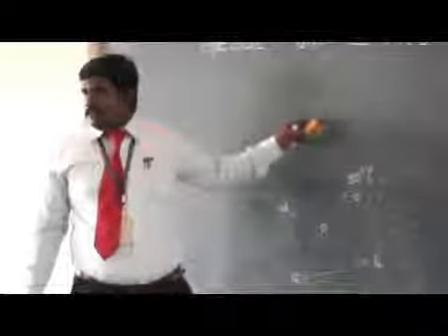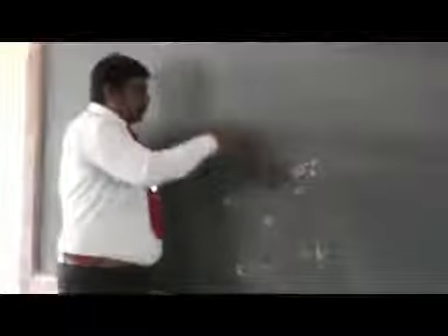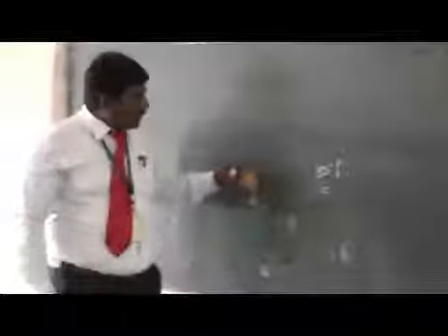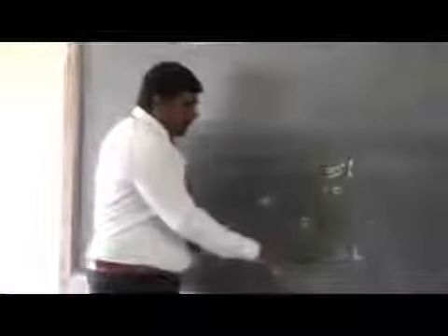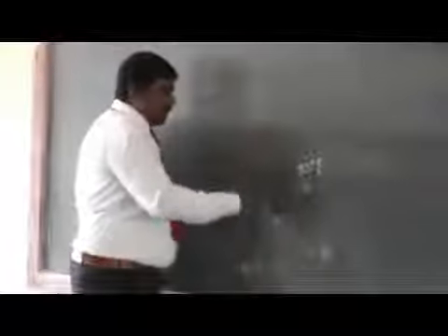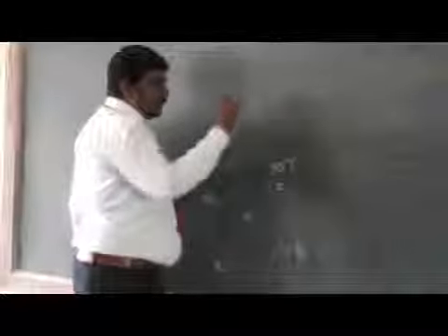Listen, 1 second. So to draw the front view of this, we have to project all the corners up to this reference line as we did before, isn't it? So now we just project all this using your draft scale so that all these position lines should be perpendicular to your reference line, and project all these corners like A, O, C, B.